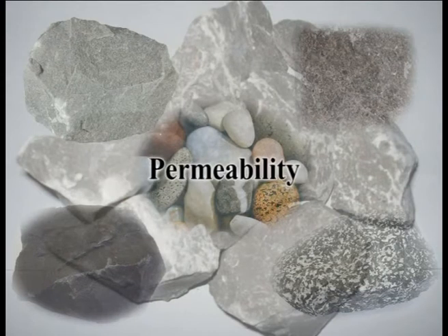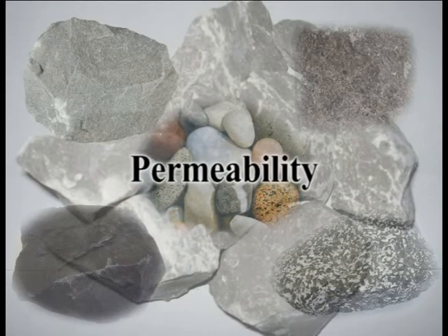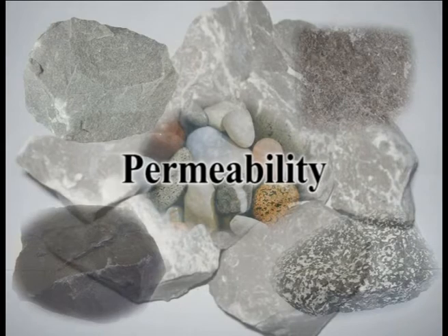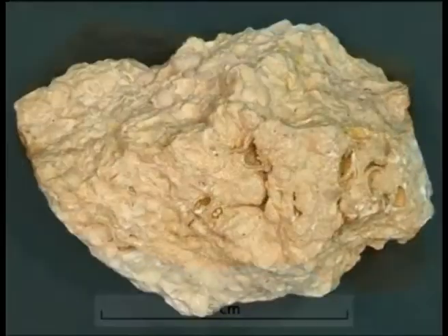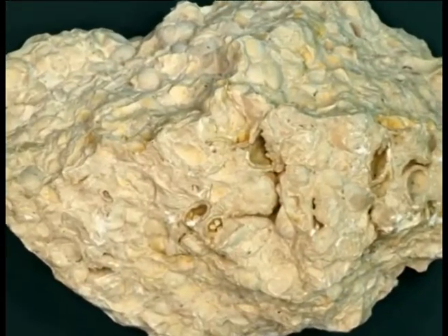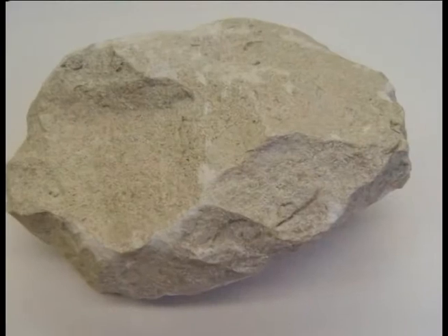And coming to another important physical property of rock, permeability. It is the capacity of a rock to transmit water. It is very important in solving some engineering problems such as those connected with dams, reservoirs, water supply and sanitary works. Sandstones and limestones may show in some cases high values for absorption, 10% or even more.